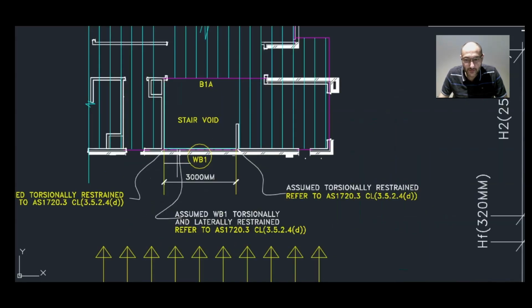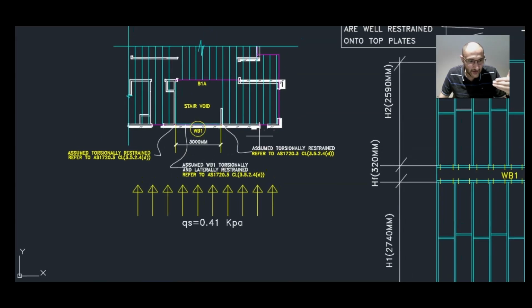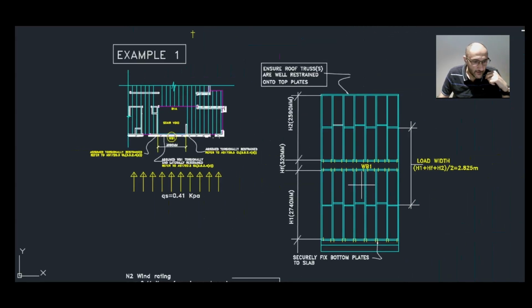Okay, here we have a 3 meter long wind beam, WB1, and that is primarily resisting lateral wind loads. Wind beams are considered to be horizontal members located between the upper and lower frames. The load from the wall above and the roof are assumed to be fully supported on the wall below the wind beam. So we will ignore the dead and live load and just take the wind loads only, and that's what the code recommends to us anyway.